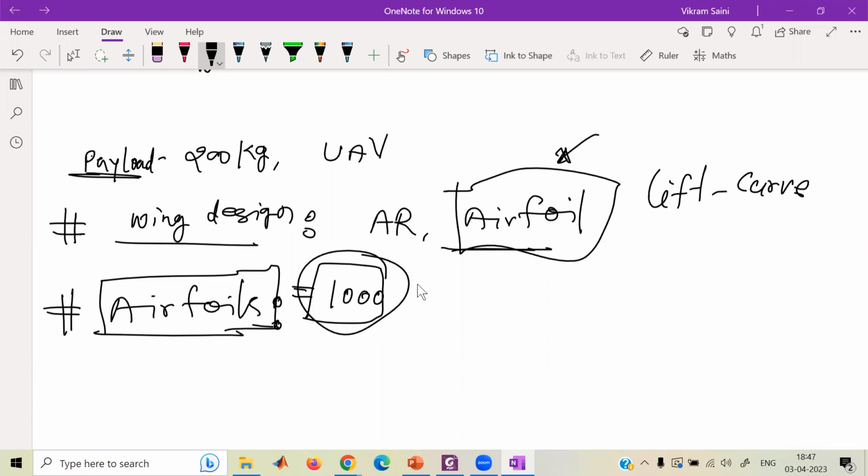For CM, for a stable aircraft with a stable wing, if we can eliminate the need for a tail surface by having the CM naught of the airfoil positive, and its slope Cm alpha negative, then we can have a wing-only design, which is very efficient, and it should produce very little drag. Means CD should be very low for the airfoil.